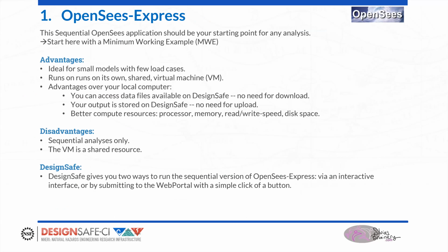I want to keep digging a little deeper into each one of these. OpenSees Express is your starting point. Now, the question is, how is it different from what I could do at home? It's actually the same program that you can run at home, and therefore it's ideal for small models and small load cases or few load cases. In DesignSafe, it runs in its own shared virtual machine.